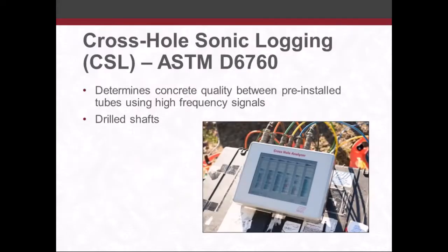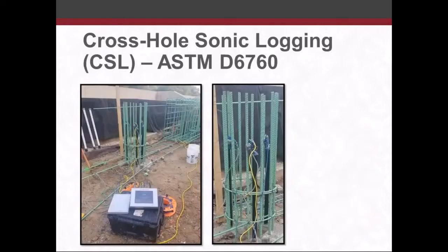Cross-hole sonic logging. This is a test that's typically performed on larger diameter drilled piers, caissons. And this determines the concrete quality between pre-installed steel or PVC tubes using high frequency signals between a transmitter and a receiver installed in opposite tubes.